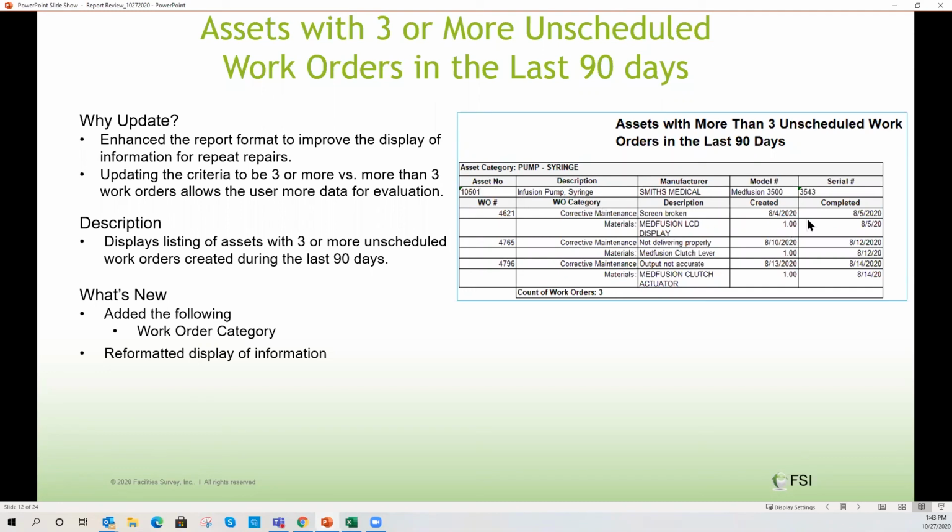And we can see that we have had some different repairs going on, some different LEDs, LCD, the clutches are going, different things that were happening. So this one is giving us a little bit of problems. That allows us to see if we're having repeats or if it's different types of repairs. So here we can see we've got clutch, so we know we've maybe got some clutch problems with this particular syringe pump.